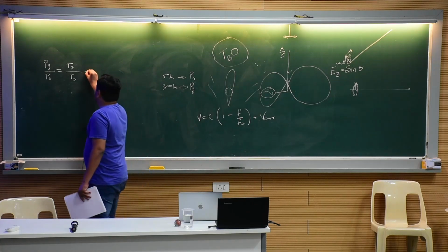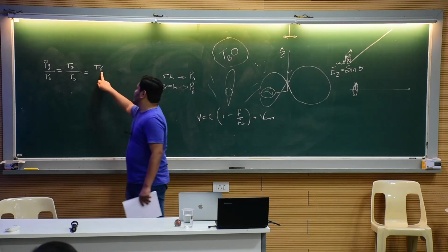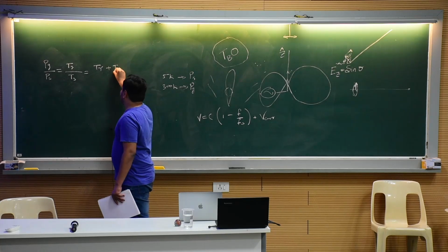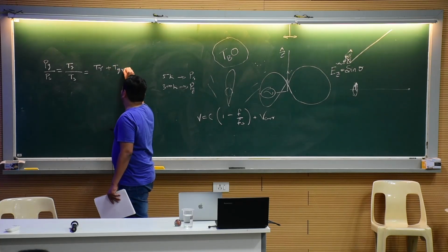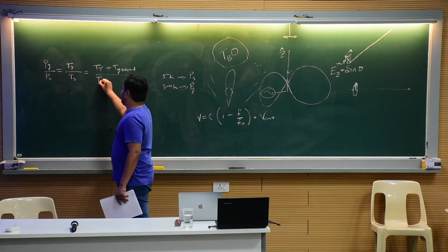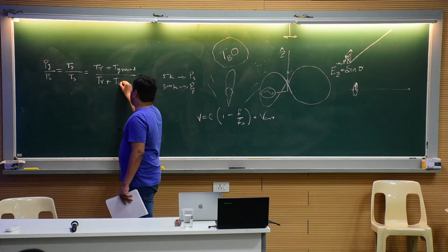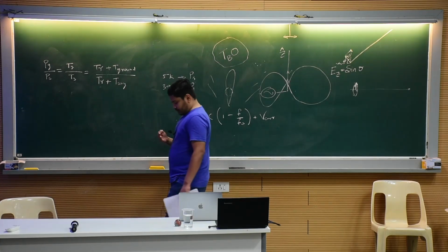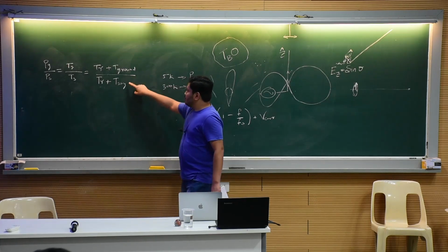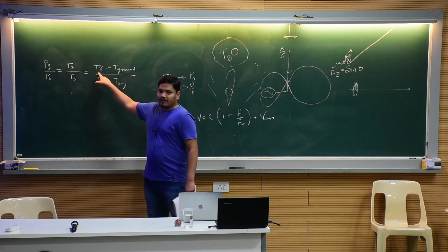And so let's say when you point to the ground, it has contribution from your system, or we call it T radiometer temperature, plus T ground. Also, when you point it to the sky, it will have contribution from your system and T sky. So these are the two values that you measured, and these two values you know. We have assumed their temperatures here. You can find out TR. TR is the receiver.